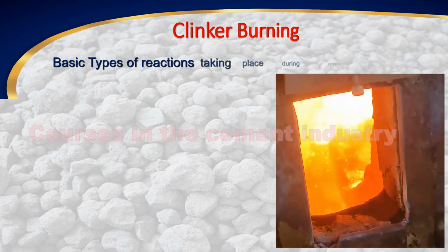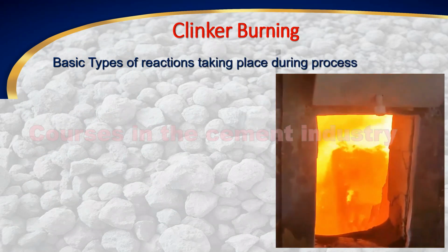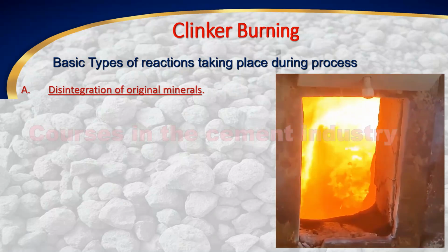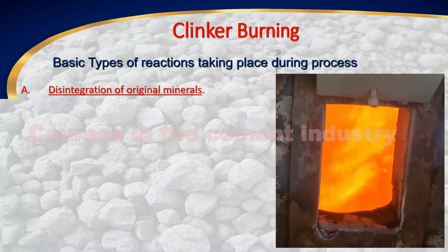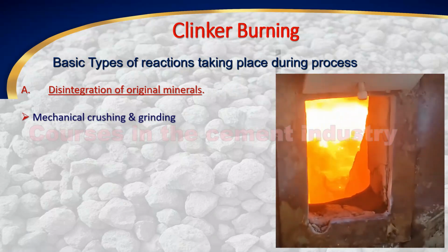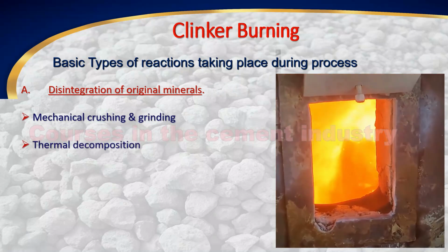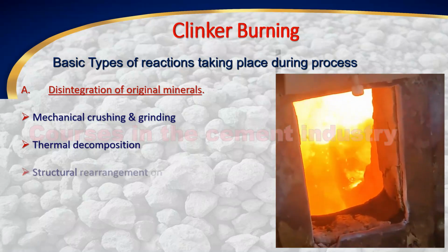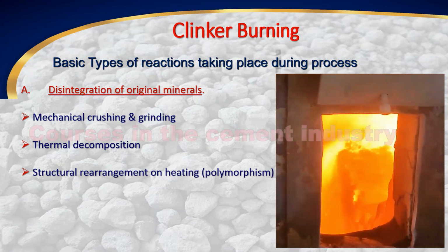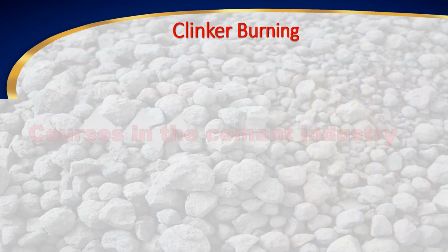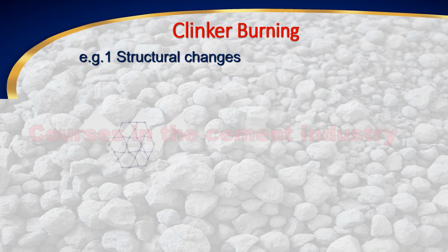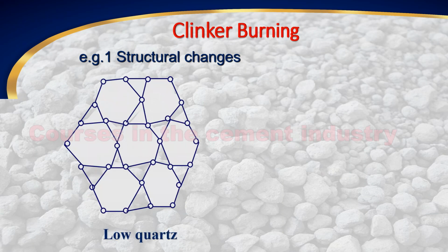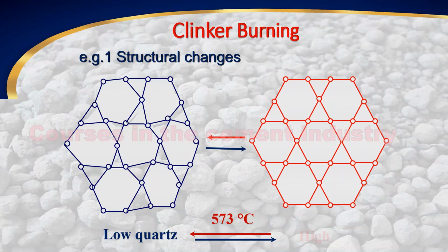Basic types of reactions taking place during the process. A. Disintegration of original minerals. 1. Mechanical crushing and grinding. 2. Thermal decomposition. 3. Structural rearrangement on heating, polymorphism. For example, structural changes. See the figure. Low quartz. A change occurs at a temperature of 573 degrees. The change occurs to high quartz.